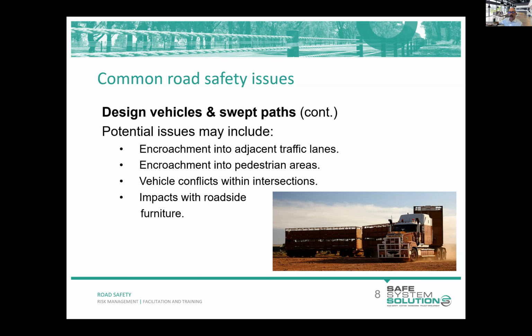Yeah. And I think it's worth reinforcing your earlier point, which is one, always good as a road safety auditor, have your eye out that it's not excessive in terms of catering for some very large vehicle that may hardly ever be there because of those dangers of very wide openings and higher speed of smaller vehicles and other issues that may be caused. I mean, it's less frequent that happens, but it's always good to have in the back of your mind. It's more the other way around. Usually they haven't been able to cater for a large vehicle that's frequently there.